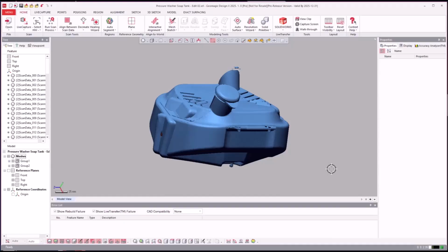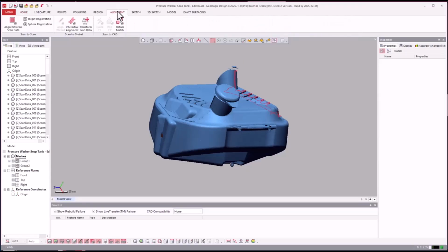And then what happens after I edit, then I align, then I merge, and then I model. I kind of have those stages in how I label. And then I even revise the model up sometimes. If I'm editing and I need to make a change that I'm unsure about, I'll save the file, do a save as, and rev it up to the next number. Instead of edit 01, I'll do edit 02. That way I have something to go back to and work with.